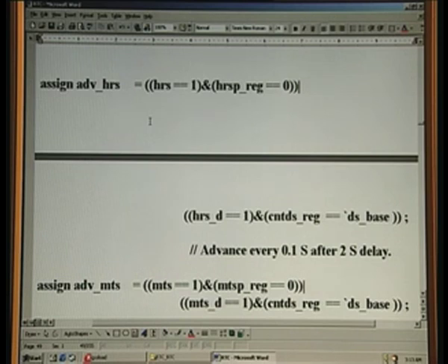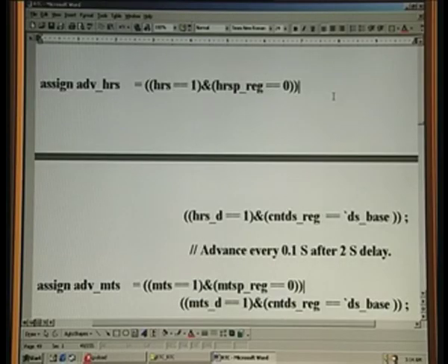For example, you push the button, it will go to 1 here, and the earlier previous value would be 0, because you have just now pressed and it has just now been recognized. So whenever you make a single push button press and release, this will come into force, whereas if you keep it pressed for 2 seconds or more, this statement will come into play. When this comes into play, then this delay will go to 1 only after 2 seconds. That is how this circuit is working.